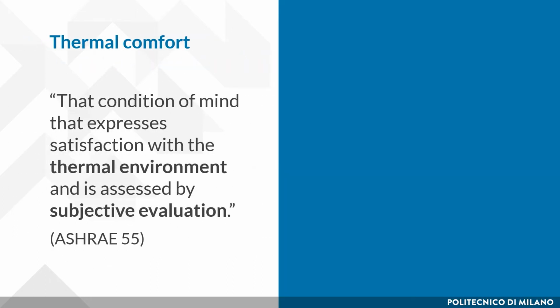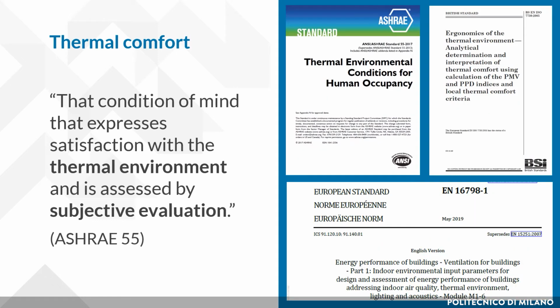Thermal comfort has been widely analyzed and is defined by ASHRAE as the condition of mind that expresses satisfaction with the thermal environment and is assessed by subjective evaluation. This means that you have to consider both some measurements of the thermal environment to evaluate comfort, some numbers such as temperature and airspeed, and also the subjective evaluation of the people experiencing that level of comfort.